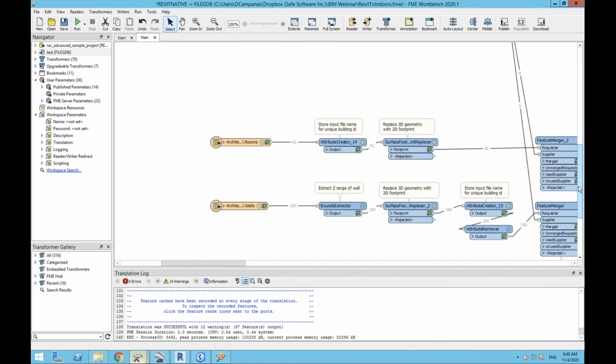So it cuts out some pieces with other pieces, and that makes things look good. But what I'm looking for is pure polygons. Now I could go in and create my own view within Revit that just has the rooms and the walls and nothing else, and that would give me what I want. I don't want all the other things like electrical fixtures clipping out my walls. But it's easier if I just grab the 3D data and squish it down to 2D, because it's fairly simple and there's not too much more.